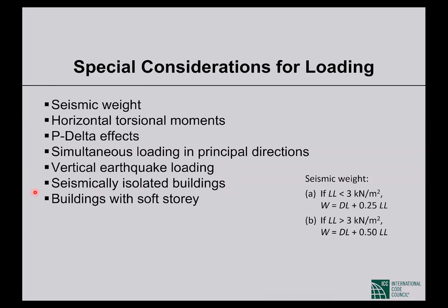Seismically isolated buildings. I don't know if you are familiar with this term. Maybe you have heard the term base isolation. Base isolated buildings have a kind of bearing at the bottom of the columns on top of the footing, and the bearings are such that they isolate the building from ground vibration.